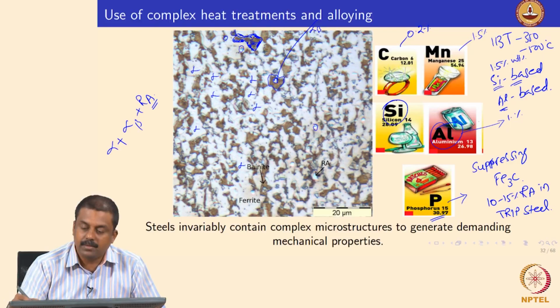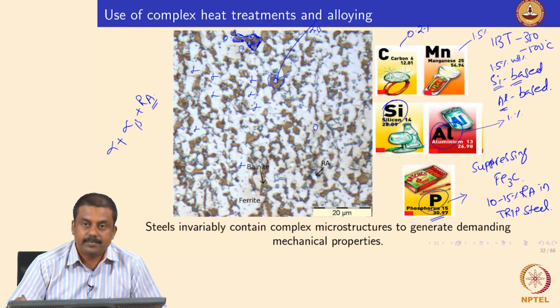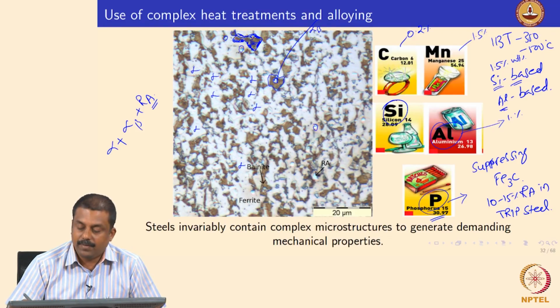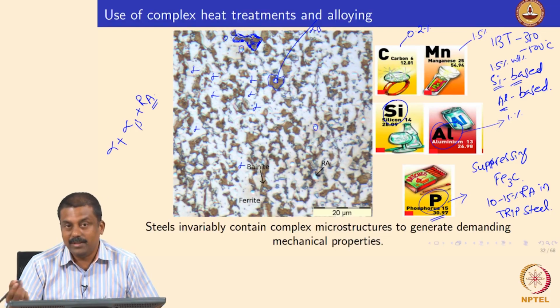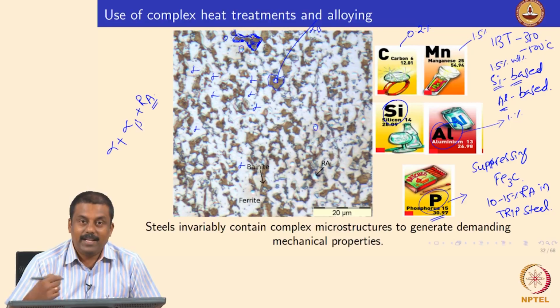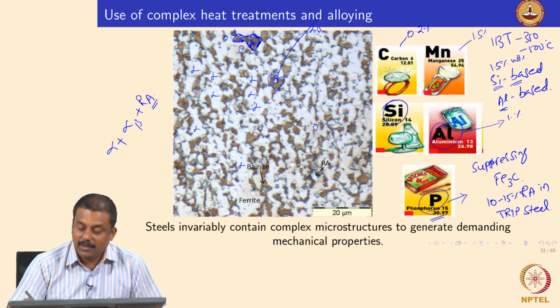So there were some developments adding a somewhat increased amount of phosphorus in steels, so that we can increase the strength in aluminum-based strip steels. But phosphorus is an extremely notorious element during welding. In terms of hot cracking susceptibility, phosphorus is extremely notorious. Steel makers generally don't worry about welding, but as welding engineers, we have to worry about weldability as well. You can add phosphorus to a slightly higher amount than conventionally used, but because of this addition, the weldability of the material is affected extremely.